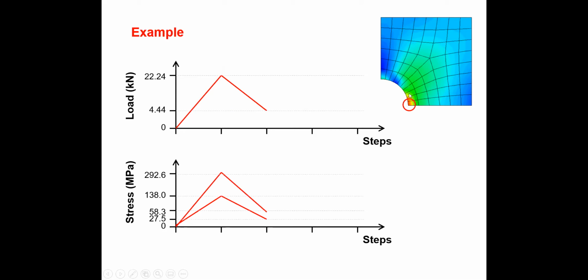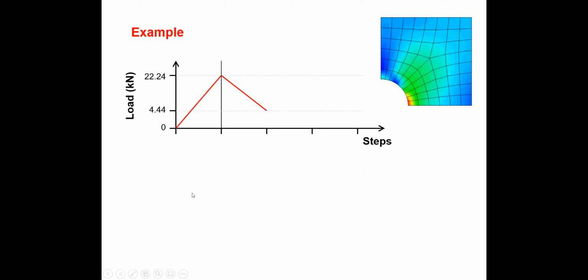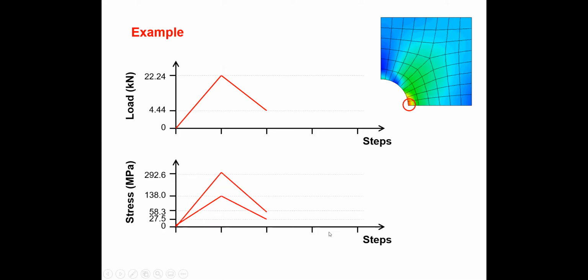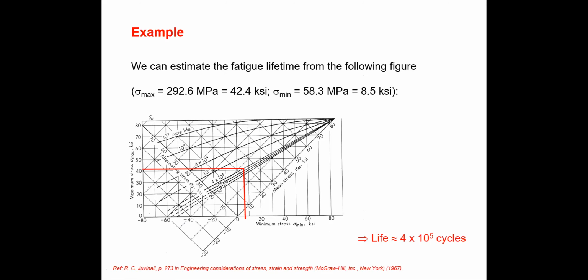This is the stress raiser. This is one quadrant, the first quadrant of the plate. Okay, this is the first quadrant of that particular hole. So you can see that at the edge of the surface of the hole, around that area, there is a maximum stress. You can see we already calculated that value here. These are the maximum and minimum stresses.